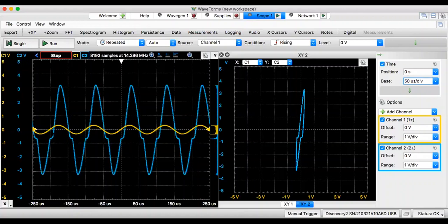Why? That's because of the design of the op-amp. So a crossover problem can be reduced, but never eliminated. We can design better circuits, better op-amps to make that crossover less and less of a problem, but it will always be there. So that's the first, crossover distortion.